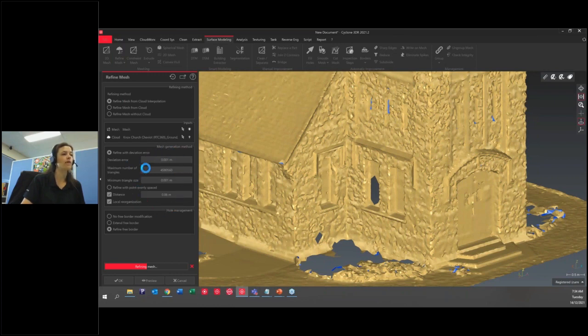And that's the tip you can try to remember when you don't really know what to do. Here, 3DR actually enters default values for you that should make sense. I see that the value at the top is quite often a little bit small. If you compute with a too small value straight away, it might take a while to compute, and at the end you're looking at something that might just not be good enough, but you spend a lot of time. So I would recommend using a deviation error that's maybe a little bit bigger, just to have a first preview that doesn't take too long. And then if you see that it's actually very quick and you can go for more detail, then you decrease that value.